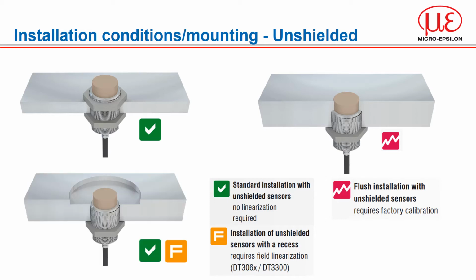Mounting an unshielded sensor flush in a recess is also possible, provided the surrounding area is non-metallic and at least 3 times the diameter of the sensor. Otherwise, perform an in-field calibration if possible.